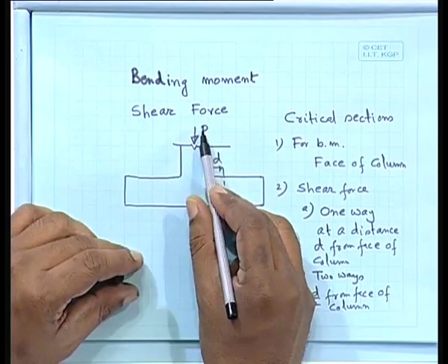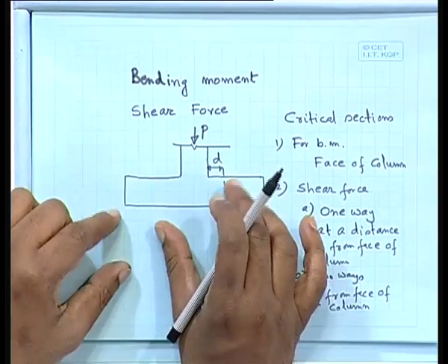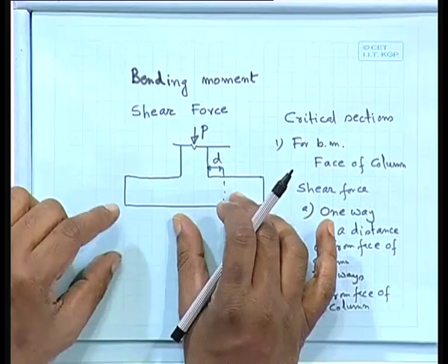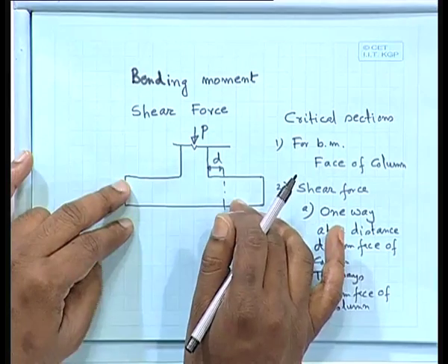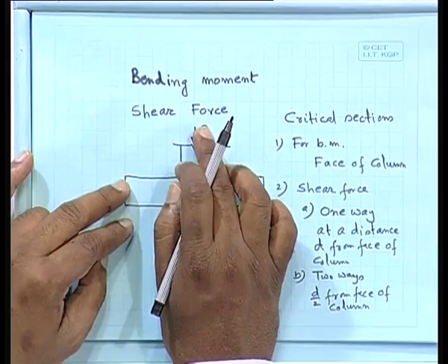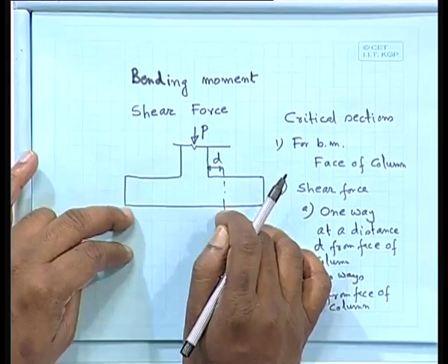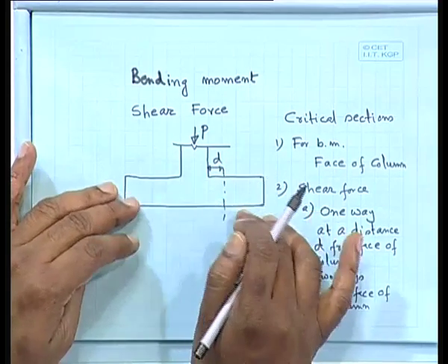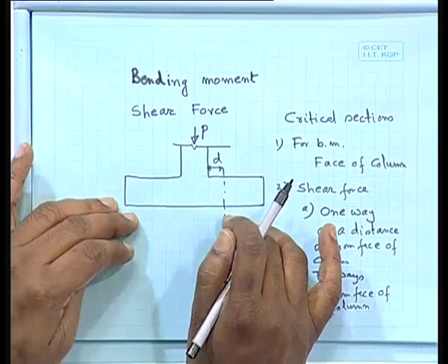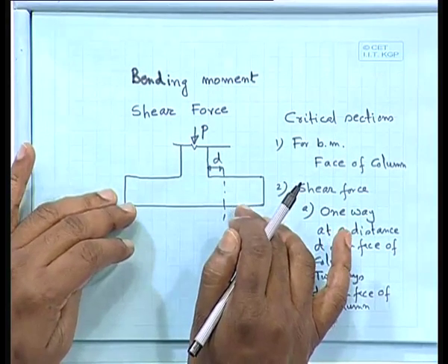remember. So, your column load, and a certain amount, say maybe 10%, you can take for the footing, because the footing size you have not yet decided. So, 10% of the axial load coming, you can take as the self weight of the footing. Considering that, you can find out the footing size under serviceable condition.